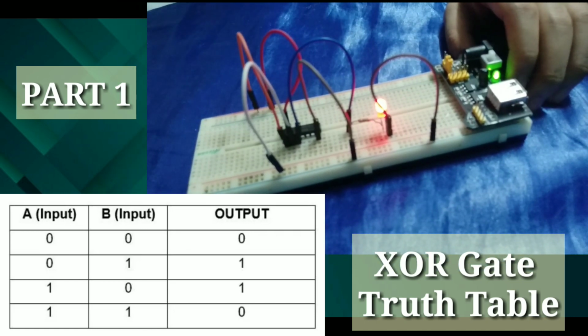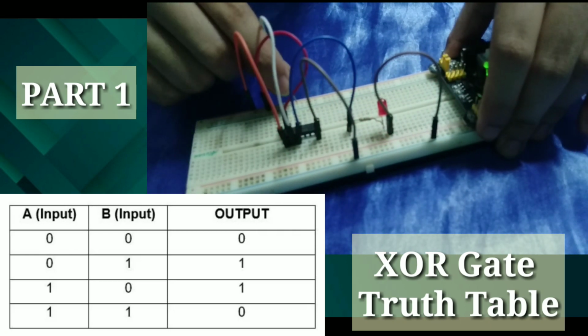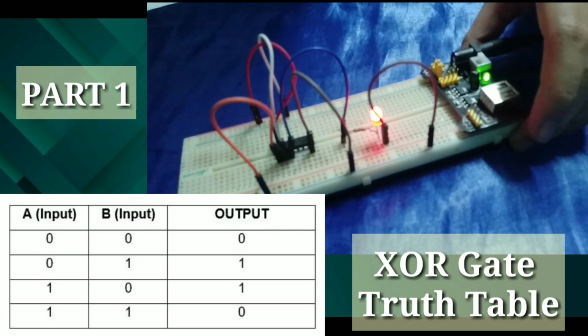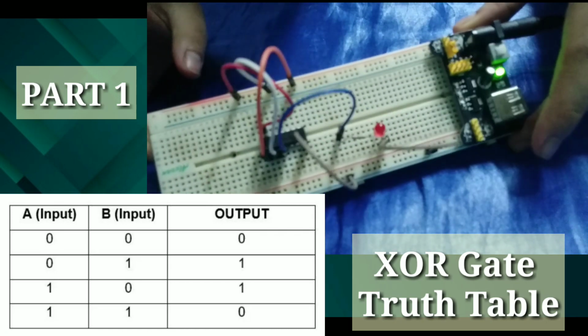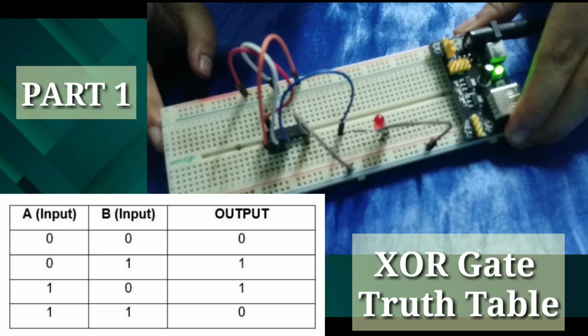Now, if A is 1 and B is 0, so let's interchange them, our output will be 1 as well. The LED is turned on. And lastly, if both inputs A and B are 1, the output will be 0, or the LED has been turned off.